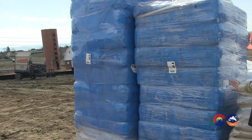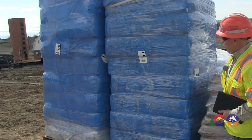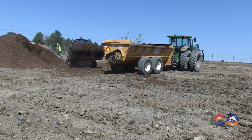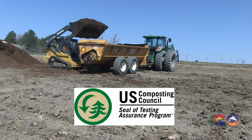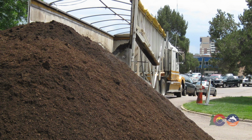Any bags where organic fertilizer or amendments show evidence of condensation or mold damage must be rejected. Compost is to be delivered in bulk. Inspect the compost certificate of compliance to ensure it comes from a U.S. Composting Council Seal of Testing Assurance Program facility. Review that the compost meets the requirements of the 212.